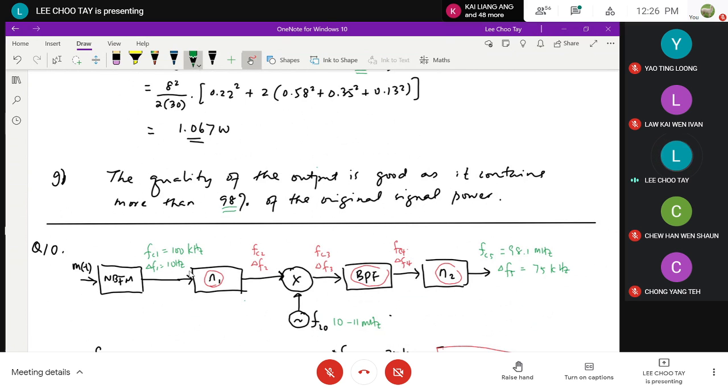Okay, so then we pass the signal through the first stage of frequency multiplication, where the multiplying factor is N1, to give us the second carrier frequency, FC2, and the second stage of the frequency deviation, which I call delta F2.